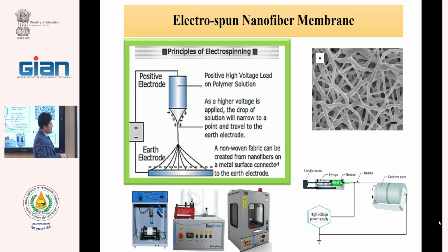We prepare the polymeric solution, fill the syringe, and apply very low pressure for injection of the polymeric solution, and the collector begins to collect the fibers, and in this collecting, the microfiber changes to nanofibers.